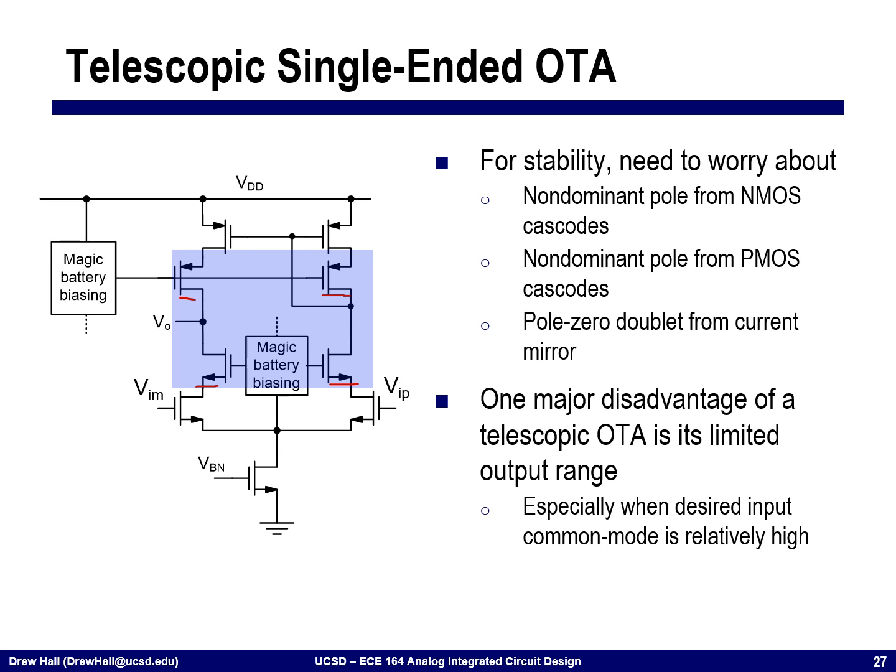However, here, you'll notice that if the input common mode voltage were to go up, and these particular devices, i.e., let's call this VBN, was biased relative to ground, what you would see is that this node here would go up, but the gate wouldn't, okay? And so what that's going to do, this node does not go up.